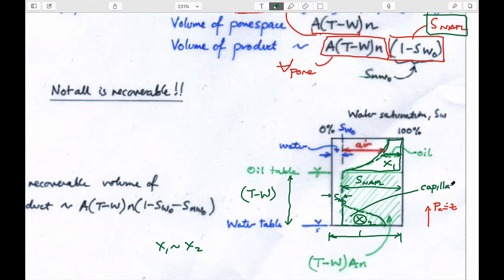Not important for us to really know that, I guess. But if we want to use this simplified way of calculating the volume that's present, which is what this is, then this green volume here is just the outline volume in this whole thing here. It's nothing more than that. It's the height multiplied by the porosity, which is the void space, multiplied by its areal extent. So that's the total volume of the pore space in the aquifer, and the saturation of the NAPL that's present within it, just a proportion.